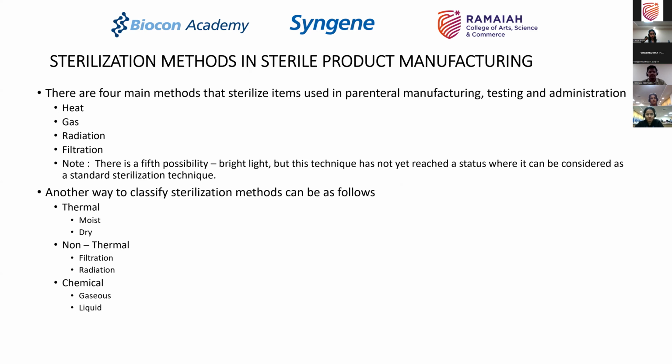Another way that you will come across in the industry is that sterilization gets classified as a thermal process, which could be moist or dry heat, where you use heat basically; non-thermal process, which is filtration and radiation, because in both these cases you are not using the physical parameter of heat as a possible means of sterilization; and chemical, which could be gaseous or liquid sterilization methods.